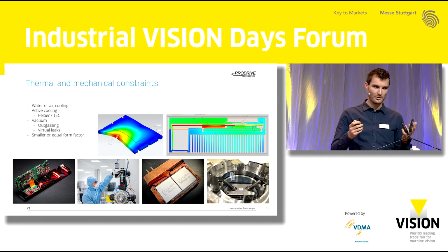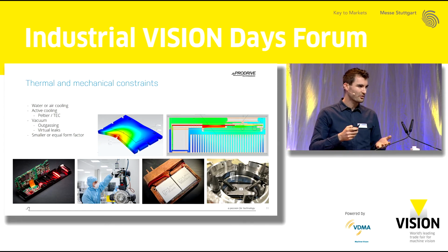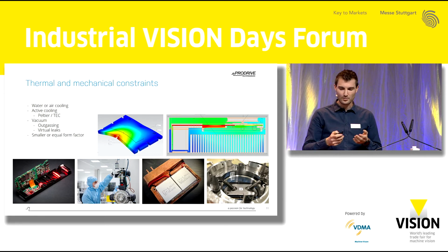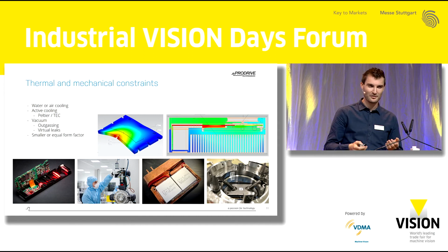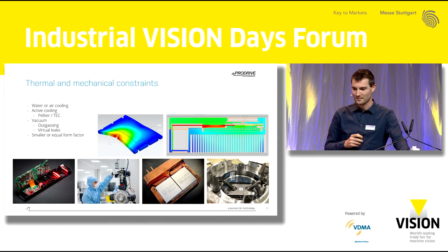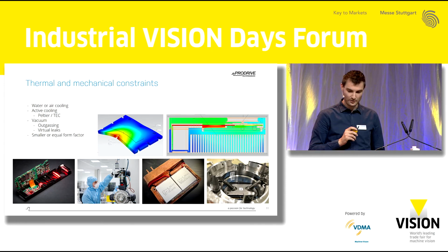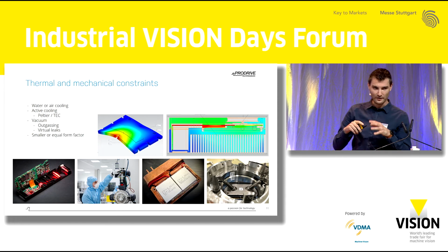Then you have the question, are we going for water cooling or air cooling? It all depends. Water cooling is slightly smaller, so a small form factor is helped with water cooling, but you need the water, so it's slightly more difficult to integrate. Then, we are familiar with doing thermoelectric coolers to actively cool down the image sensor to get sufficiently low noise.